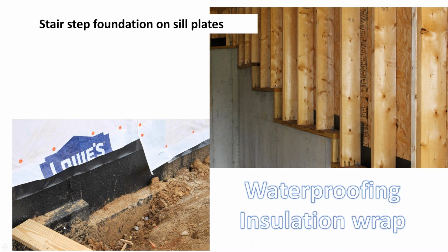And then you can see they have sealed this foundation with a tar-like substance to help with the waterproofing as well. Because again, all concrete cracks, and if you have this waterproofing substance on here, it should help with that water intrusion.